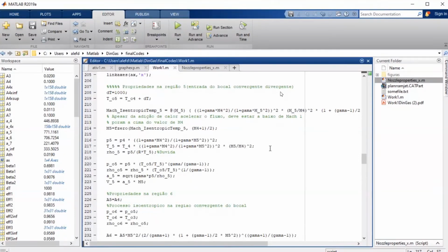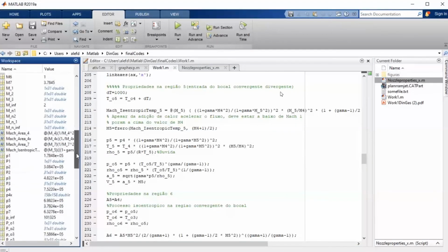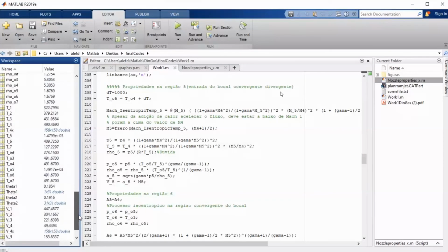When we add to the static temperature, we are not taking into account the acceleration of the flow with expansion, and in this case we lose a bit of accuracy. As you probably saw, T05 and T5 are very similar. The difference between them may be 1-2%, not so much. They are really close to one another, and in this case you do not lose too much.